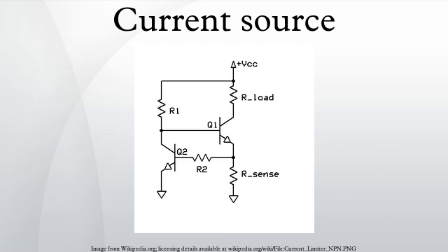Due to transistor action, emitter current IE is very nearly equal to the collector current IC of the transistor. Thus, the load current is constant and the circuit operates as a constant current source. As long as the temperature remains constant, the load current will be independent of the supply voltage, R1, and the transistor's gain. R2 allows the load current to be set at any desirable value and is calculated by the equation given,